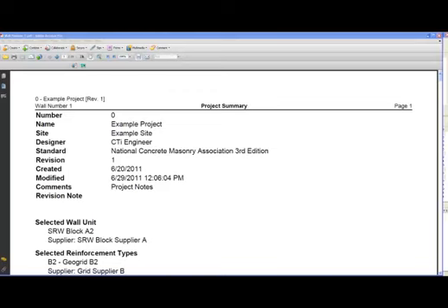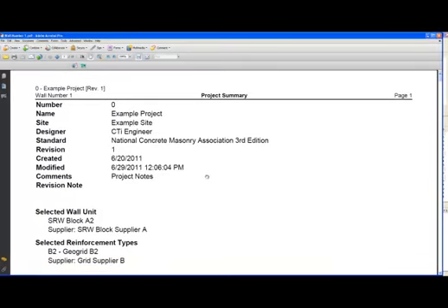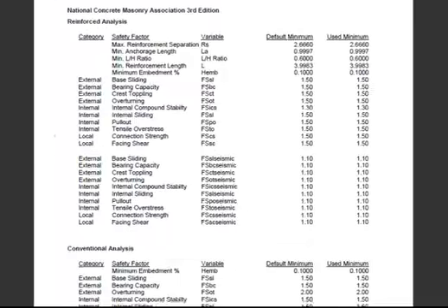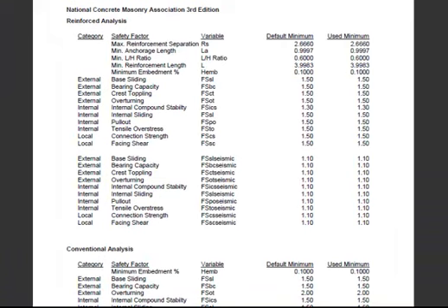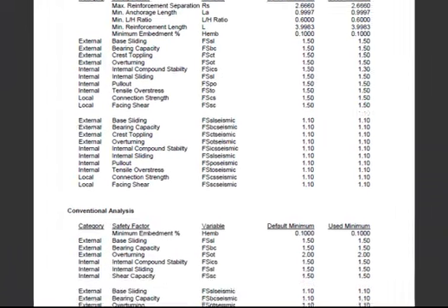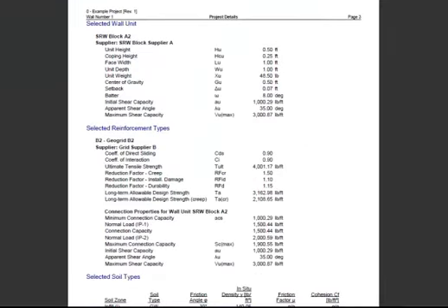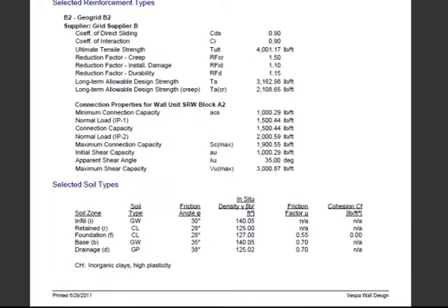The front page of the report is an executive summary of the wall. This includes the project information, block and grid type, and the total quantity summary. The next few pages detail the design methodology and various related constants, maximum and minimum design limits, etc. This is followed by more detailed block and geogrid data and design soil properties. Next, the wall layout or geometry is defined.